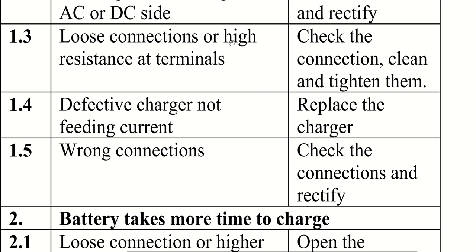Loose connection or high resistance at the terminals. Sometimes it so happens that because of the sulfation on the terminals, the high resistance contact does not make properly, and that is why it does not charge.